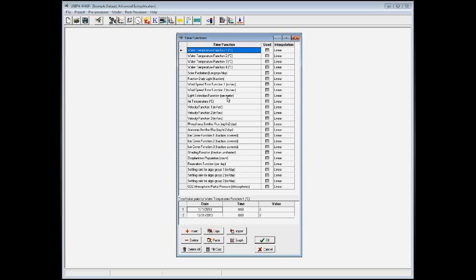You can have a light extinction time function if you're not going to let the model calculate it. Air temperature, water velocity, phosphorus and ammonia benthic fluxes, ice cover functions, a shading function, zooplankton population function, reaeration function, time variable settling rates for the algal groups, and then a varying CO2 atmospheric pressure that would be used in the pH calculations.